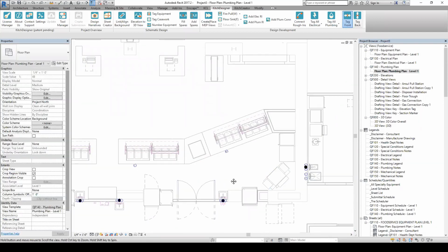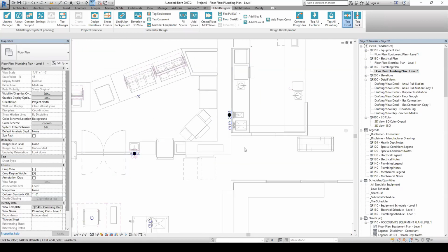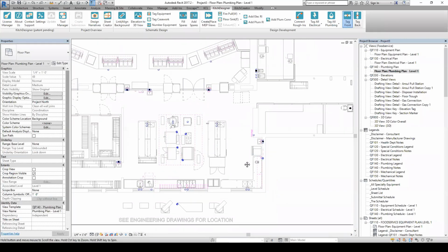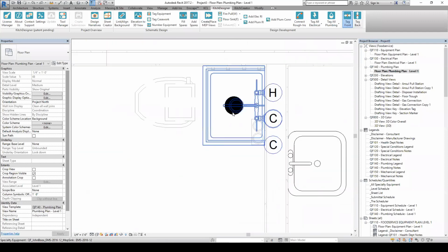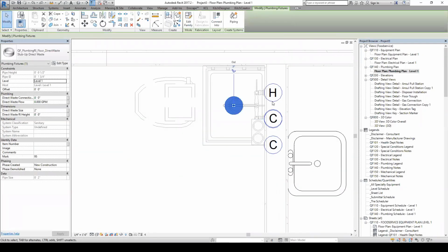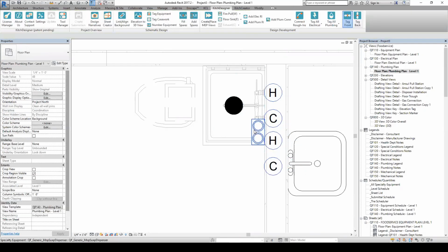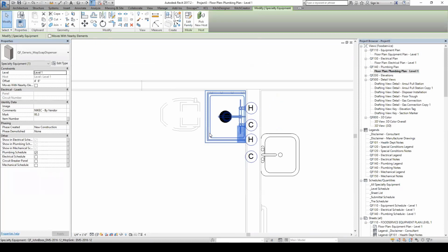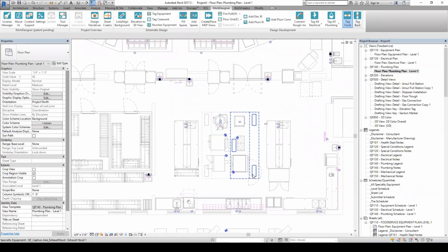Over here, hand sink and a work sink. And here, this mop sink, this is our direct waste and our faucet, and I believe this is the hot and cold for the soap dispenser. So those are all of our plumbing rough-ins that we have placed.